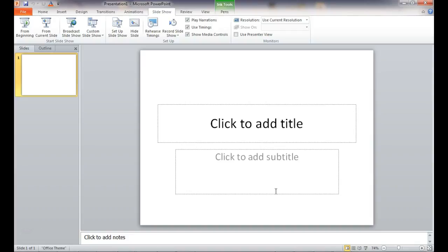But we have two ways we can send data. We can send it synchronously, which means everything is timed with a clock. So everything inside this computer is timed with a clock. The problem with synchronous data transfer is it adds more conductors and it becomes more complex. So just about all our interfaces now are asynchronous. So this is asynchronous, which means we send it without a clock. But what we do is we send it at a precise rate.